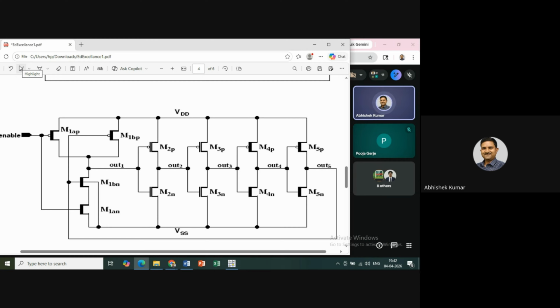How to generate frequency with the help of enable. Here we don't have a way of providing an assumption of an initial value, but we are enabling the circuit itself. So one NAND gate followed by the inverter stages. So in total we have an odd number of stages.